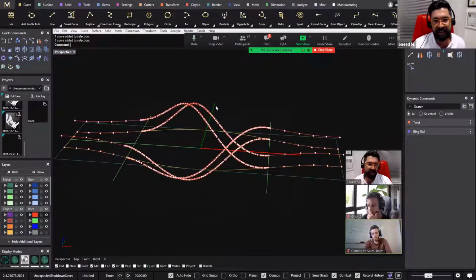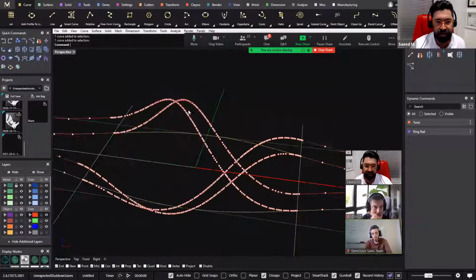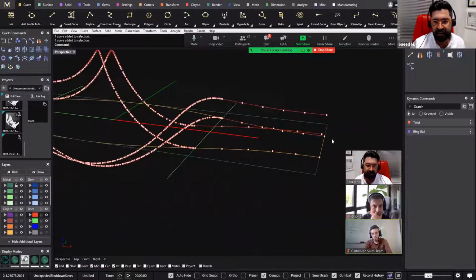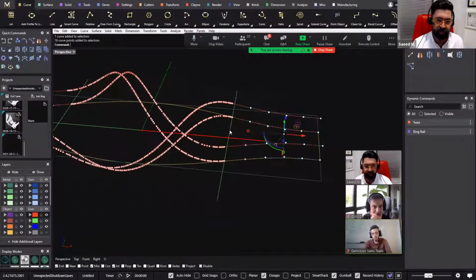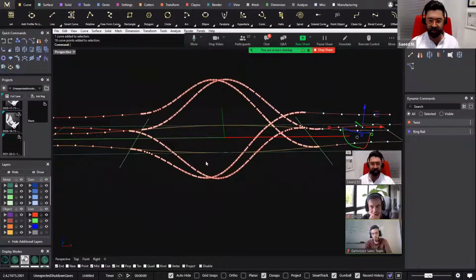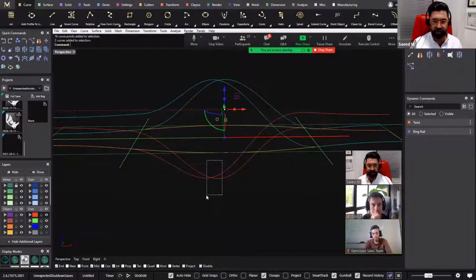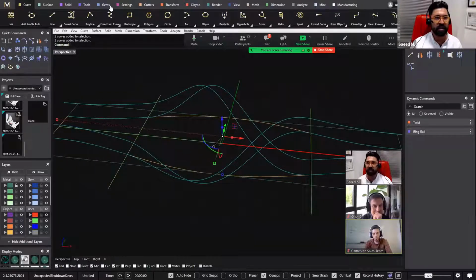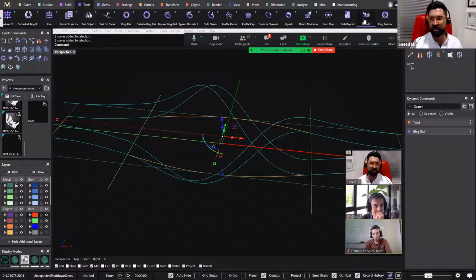Using the control points on, you can see in the area which twisted, there are too many control points. And the area that was extruded has fewer control points. If you want to work with the control points and adjust your model, you always need a minimum number of control points. It's very important. So I'm going to select these 4 curves, go to the tool menu and use the rebuild command.